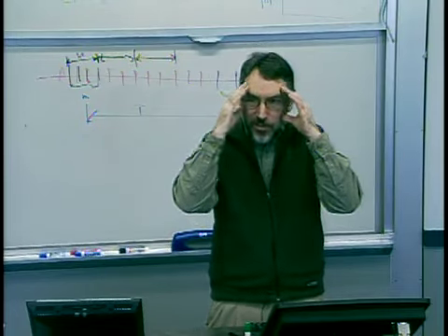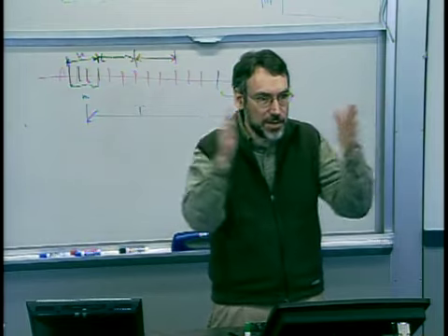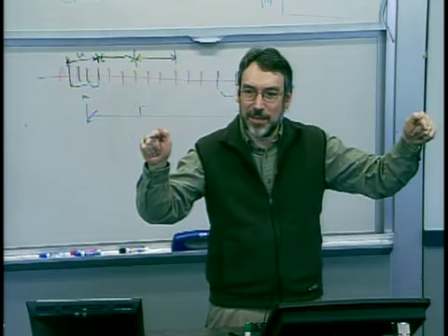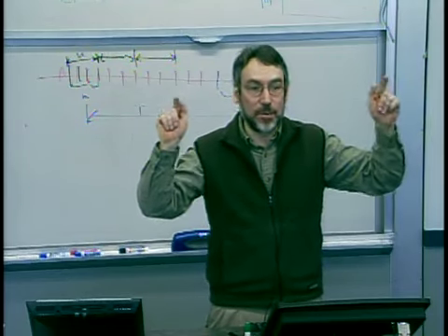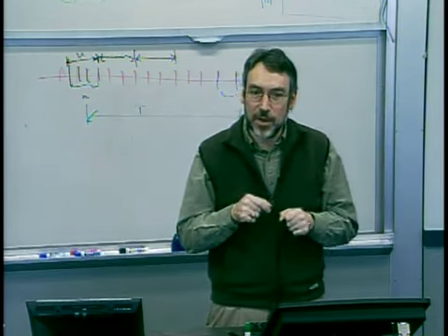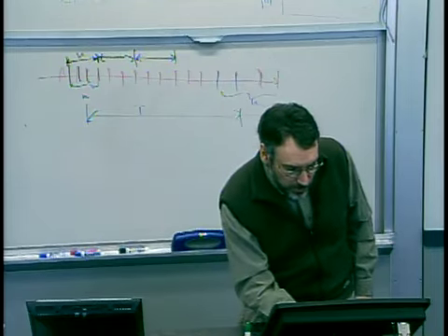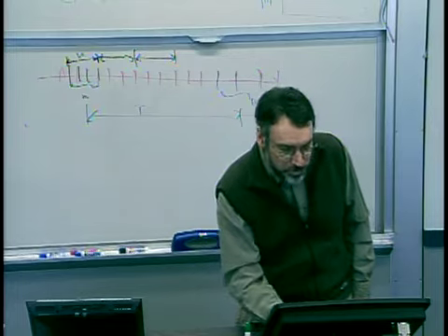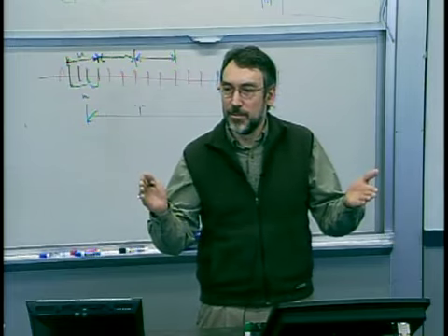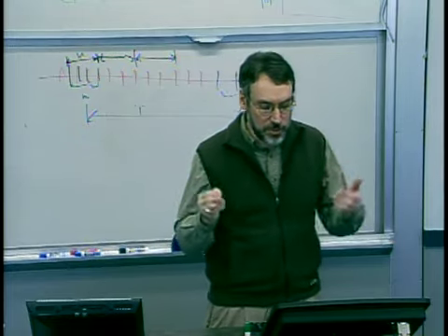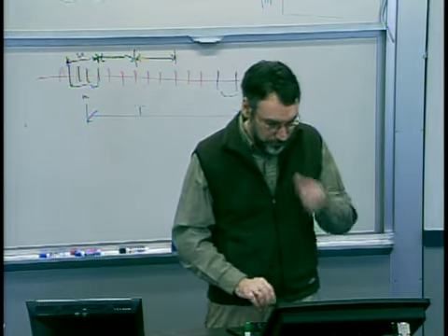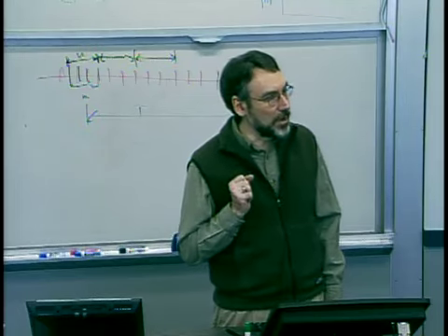So qualitatively, CP of 1, you should mesh in your mind, just says my spread is such that my plus minus 3 sigma tails are right at the spec limits, if I'm perfectly centered. Okay? And as pictured here, I am perfectly centered, so my CPK is also 1. In other words, my minimum distance between mu and my upper spec limit, or mu and my lower spec limit, is both 3 sigma. So the minimum of those two is still 1. So my CPK is 1. Okay? Now let's consider a slightly different picture.